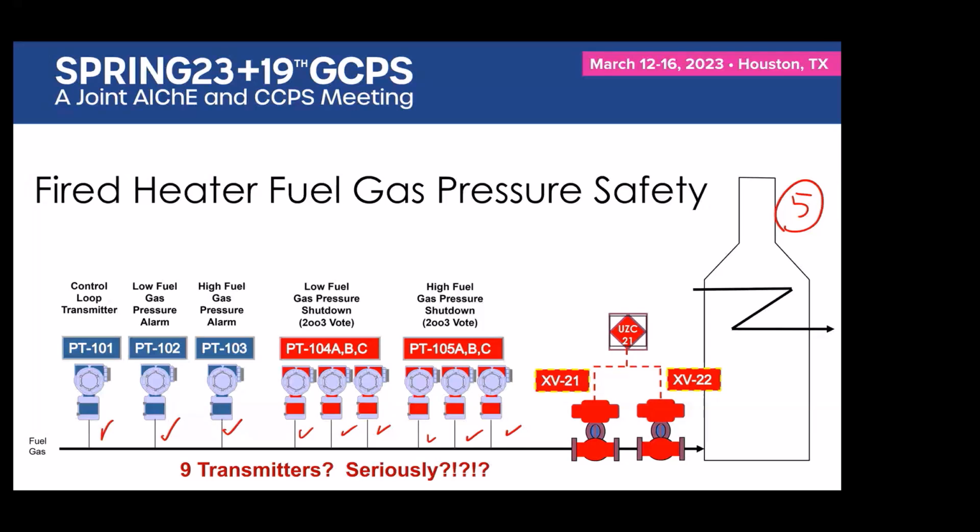Adding a third transmitter in addition to the second transmitter is marginal to negligible benefit. The fourth transmitter gives you absolutely no benefit whatsoever. It disappears in the insignificant digits of the common cause failure probability. So what are we doing?